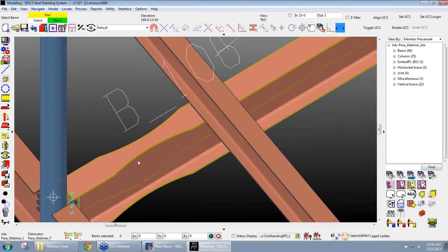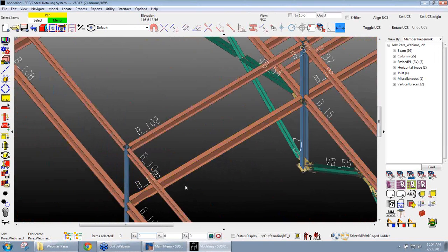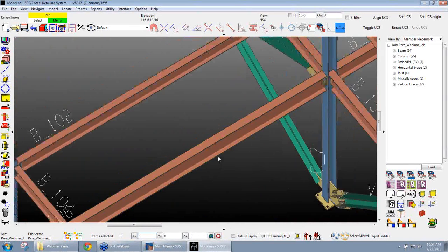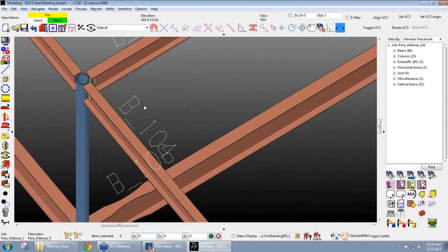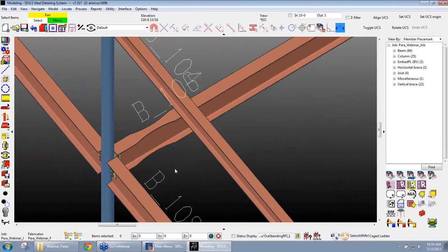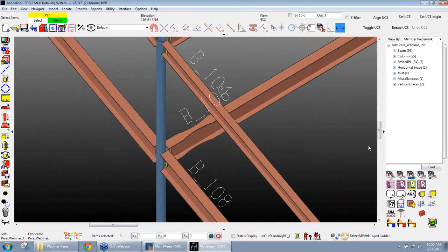There we can see we quickly got the reduced flange scenario on this left end of this beam. Like I said, I did not specify the right hand side. Like I said, very basic, but can be very, very useful and save you a lot of time instead of trying to model in something to fit around here, or potentially doing some type of cut layout to make those cuts on this.